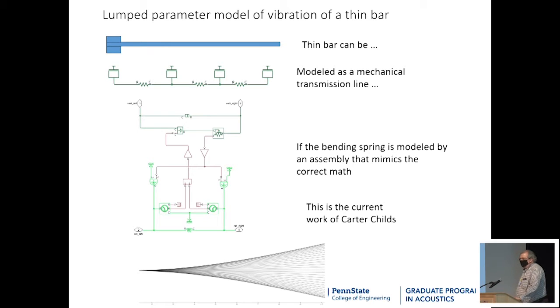Another system that is fairly straightforward is flexural beams. It's long been known that you can do a transmission line model for a simple linear transmission line, but making that into something that deals with the rigidity of thin beams simply means changing the way the stiffness of the spring is calculated to include the rotational bending and the flexural stiffness.